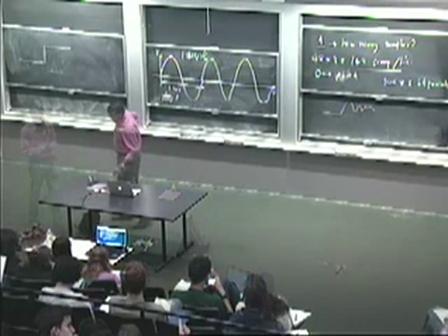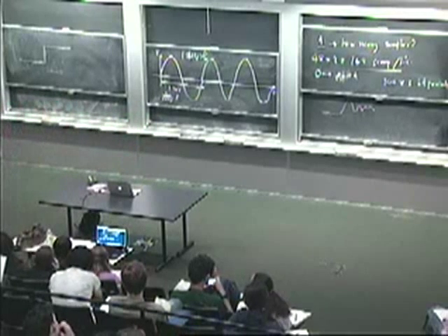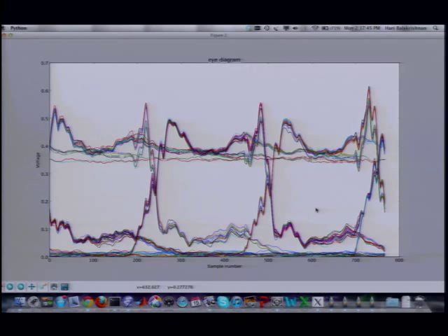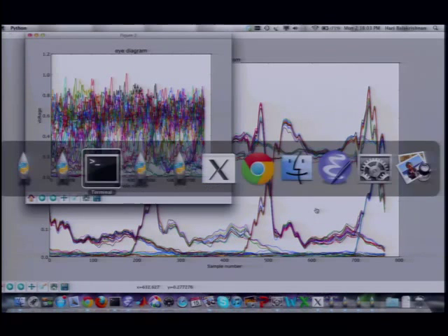Okay. We've been talking about modeling the baseband channel, and we've said we'll focus on LTI channels. So I just wanted to take advantage of this being up here to have you think about what this tells you about how close to linear this channel is and how close to time invariant it is. What we're seeing here is, for instance, a step response to something that's at 0 and then goes up to 1 and stays at 1.